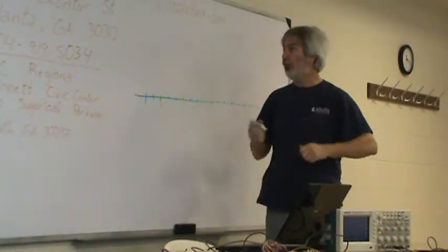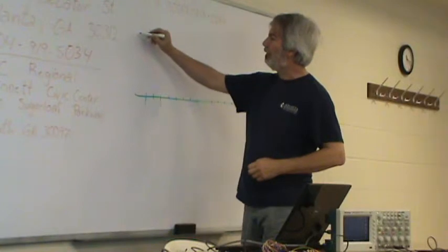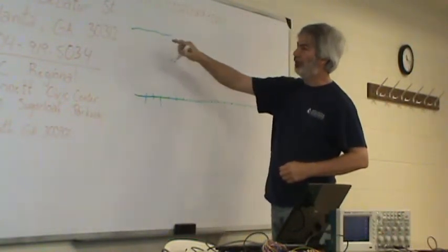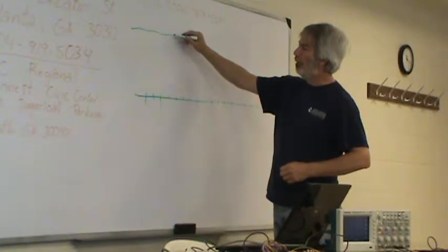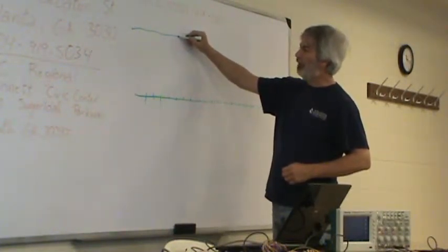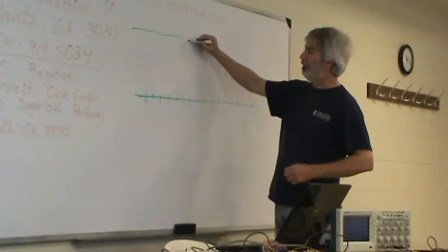And at that point, what you will actually see on your scope is your voltage going along, assume that's a nice straight line, but every now and then when you exceed the current, you may very well see this output voltage dip.